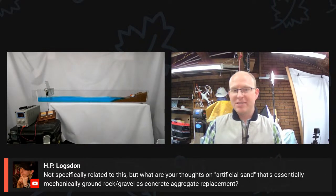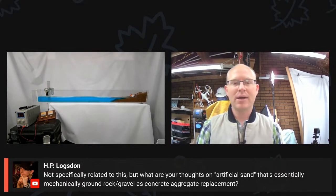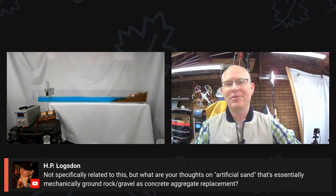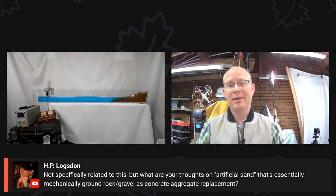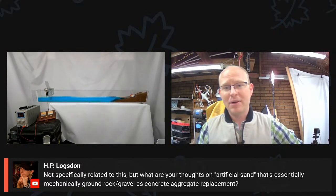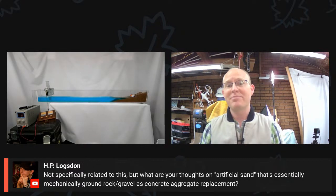HP Logson says, not specifically related to this, but what are your thoughts on artificial sand that's essentially mechanically ground rock or gravel as concrete aggregate replacement? And this is something that is very common these days, especially if you have quarries nearby that are crushing rock anyway. A lot of times you can just sift and get artificial sand anyway. And a lot of times you have sand that doesn't meet the specifications for the concrete mix design, and so you need to supplement or change the size of the grains in some way to get it to meet the specification.